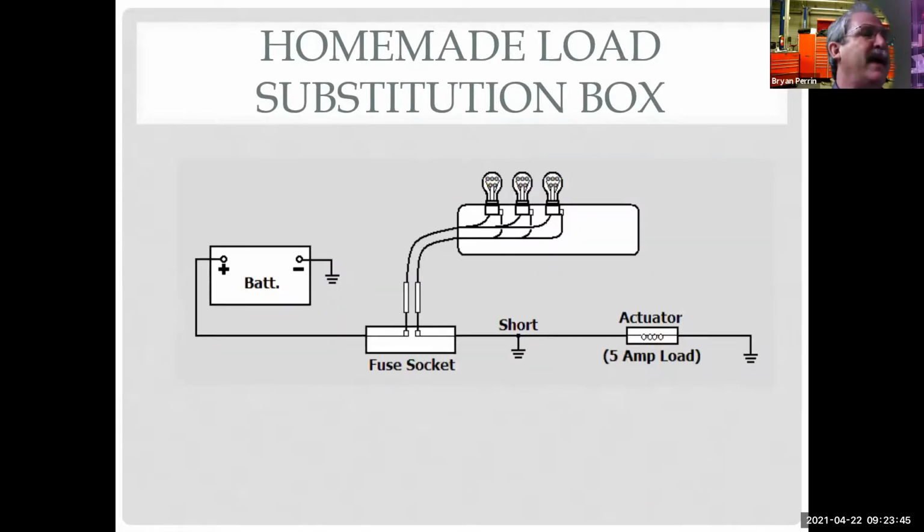So here's an example of where we use this on a car, where I have battery power and ground. I have a fuse that keeps blowing because the wire is rubbed through and shorted before it gets to my load.